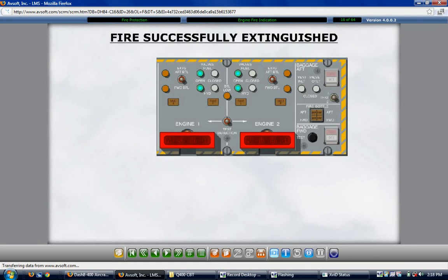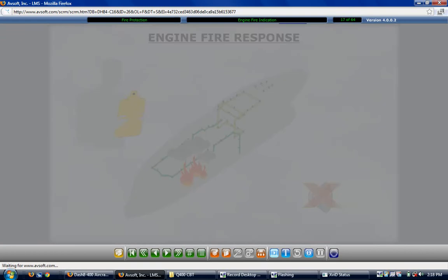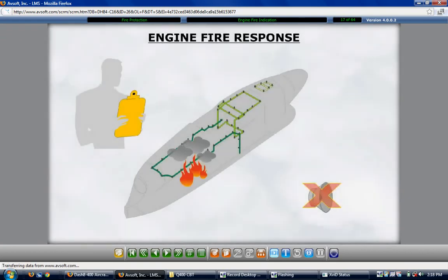An engine fire requires the flight crew to respond with their company's required memory items and appropriate quick reference handbook or emergency procedures checklist. Generally, canceling the fire bell and pressing the master warning push button is the crew's first step. This resets the system to alert the crew of any further fire dangers. Additionally, the engine has to be shut down prior to an extinguisher discharge.